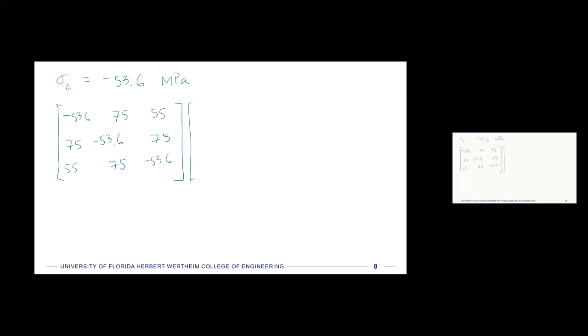And now we're on the second principal stress. So now we have L2, M2, N2 instead of the ones. Right? And if we solve for that solution, we get L2 equals 0.56. M2 equals minus 0.19. Oh, whoops, that should be M, not L, and it should be a 2. Okay, and then N2 equals 0.80. Okay. So these are all very reasonable values on a cosine plot.